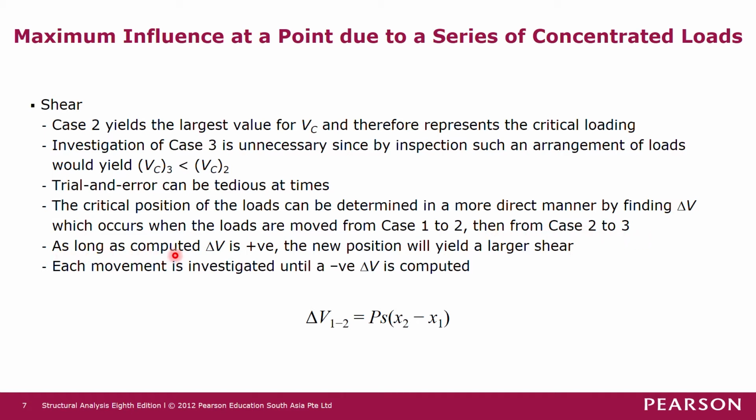As long as the computed change in shear is positive, the new position will yield a larger shear. This is obvious: when the change in shear is positive, the shear force has increased. Each movement is investigated until a negative change in shear is computed.